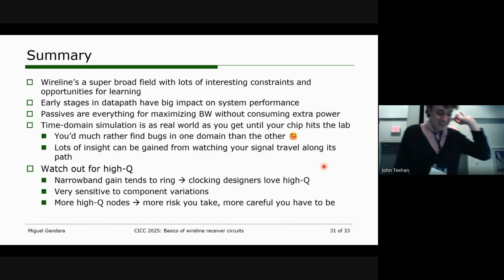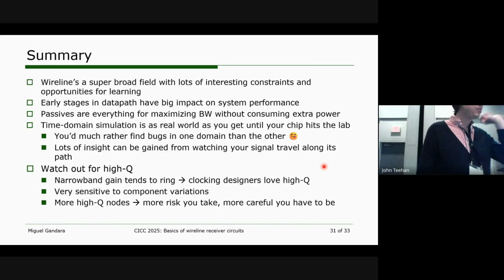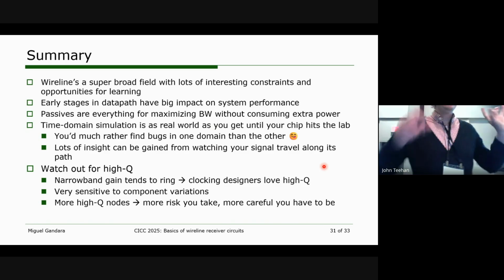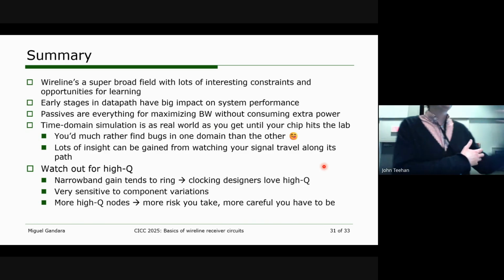So, whatever you're designing, you should be doing a step response. You should look at the step response of that circuit and make sure you understand everything that happens within it. I think you'll get a lot of insight from that process and become a much better designer as a result.